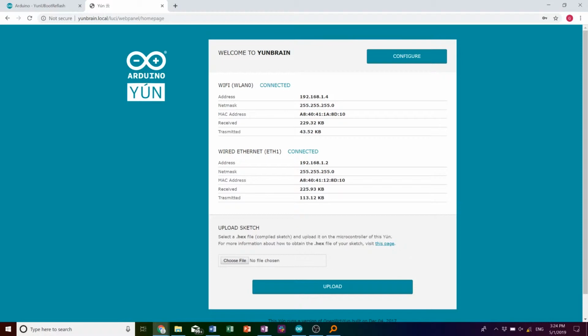Anyway, now we're going to get into how to flash the YUN with the new bootloader, operating system, and images, the three files required to get this YUN with an operating system that'll be able to install different Python packages. Because out of the box, while Arduino claims it works, I've never had a YUN that worked out of the box with this. So these are the changes that I feel like we have to make.